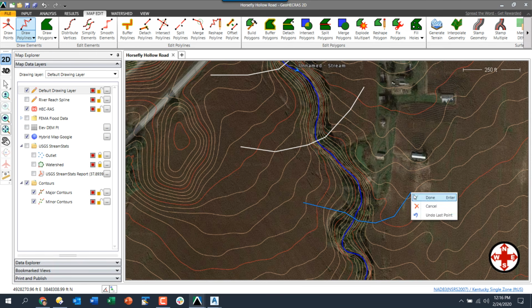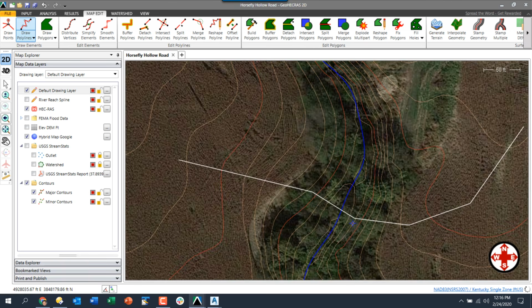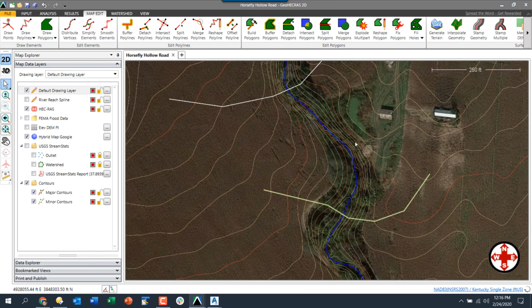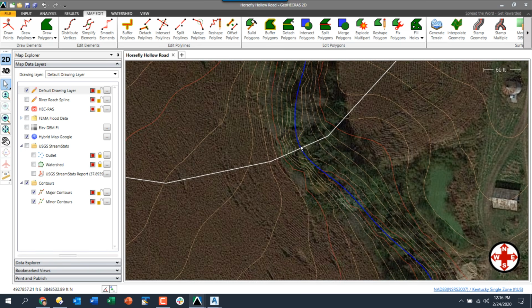Now, another little trick I do is I always try to figure out where the thalweg is. So here I can see there's a low spot. So where I cut my section is not really catching it. So I might actually pull that line down to capture that contour right there. So you might want to go and check that here. Here it looks like there's a contour line right there. So maybe I want to adjust that down. Now we're pulling off a DEM, so it doesn't much matter. But if I still want to catch that contour, again, I can press function key F4, insert another vertex, and just pull that vertex down and kind of capture it.